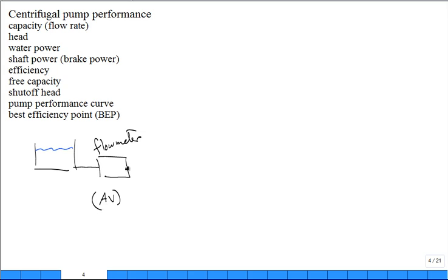Then it's good to have valves so that we can control things. With this valve, if I need to work on the system, I can shut it all the way off and then disconnect everything to the right of it. Or it could be a throttling valve where I close it a little bit and give some resistance to the flow across the valve. Or I open it all the way up and let the flow go through with minimal resistance. Think of it being fully open, fully closed, or even partially closed.